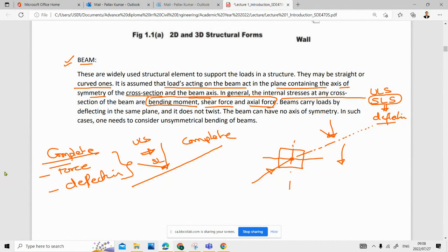You can't ignore service conditions, because they reflect the deflection component of your beam. So for complete analysis, force and deflection are required, and for complete design, you need to design for the forces in the system and also look at its deflection. Is it clear?